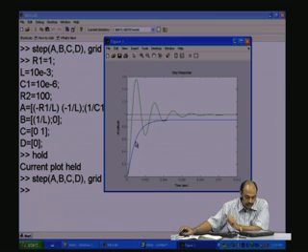Here, you will see the poles. Now, here there are 2 energy storage elements, therefore, there are 2 state variables, and therefore, it is a second order system, therefore, there will be 2 poles. So, the number of energy storage elements is going to directly influence the number of the poles. If there are n energy storage elements, there will be n poles. So, there are 2 energy storage elements. In this situation, both the poles should be somewhere close to the real axis or on the real axis.